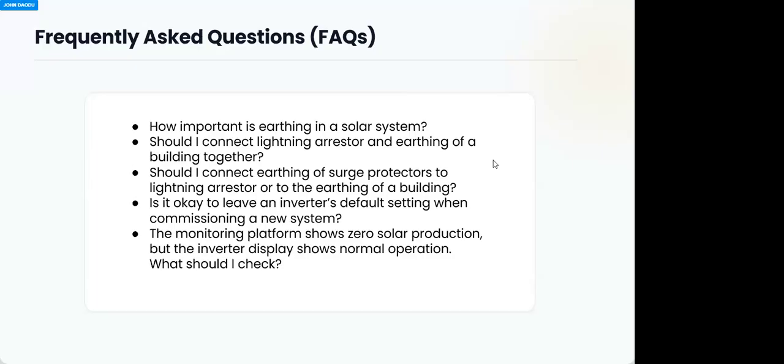Now, a circuit breaker does not know the voltage level you are applying to it, but it is rated. The manufacturer will tell you that this circuit breaker can withstand so much voltage, meaning that if you exceed the voltage, there could be arcing. It can jump the breaker when it's off, because it is rated 20 volts and you're applying 100 volts. When it's off, 100 volts can jump over and send a wrong signal to another place.